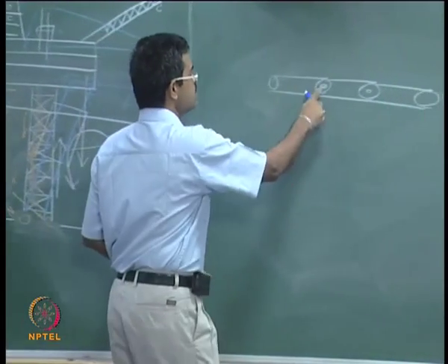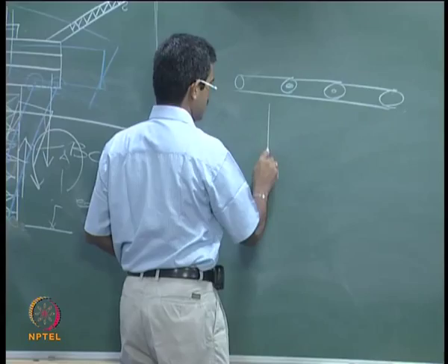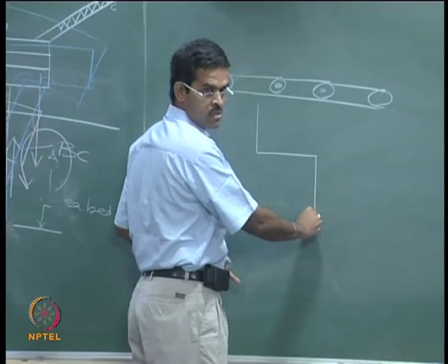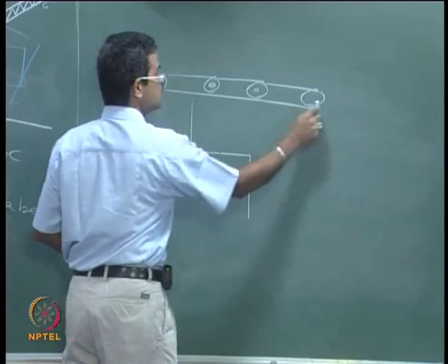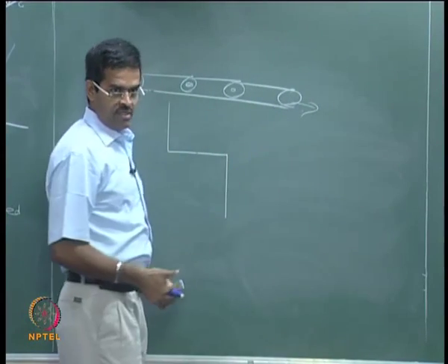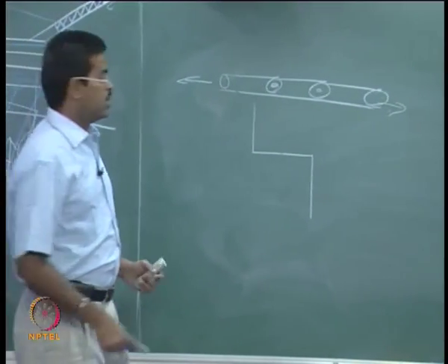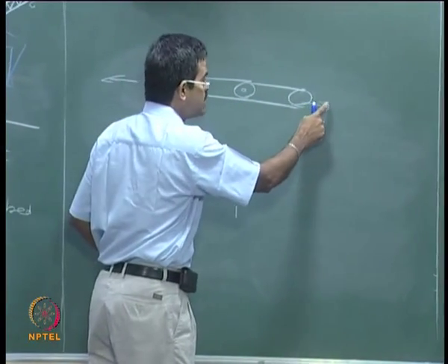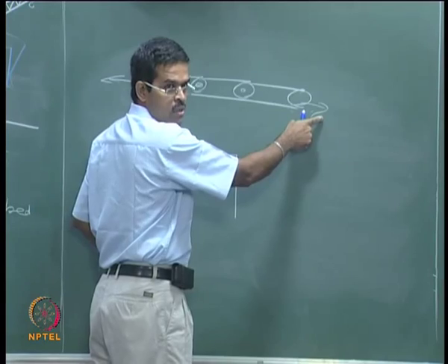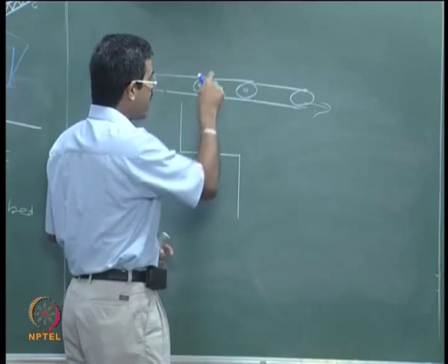Even though these hinges give flexibility to fold this in any form he wants, it requires a basic axial force to make this rod straight. Okay. So, multiple hinges introduced in any member need a basic minimum axial force to straighten this member or to keep this member straight.